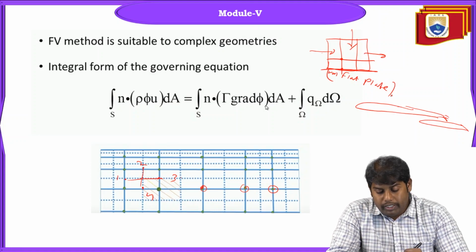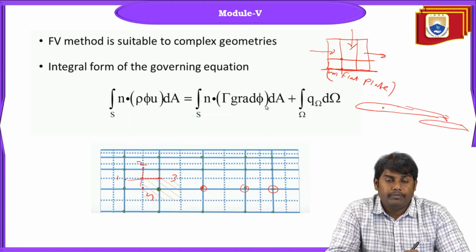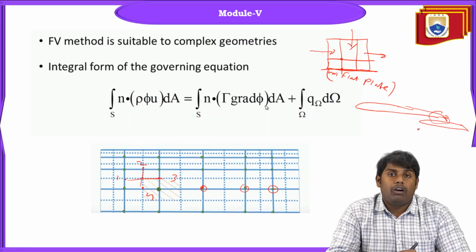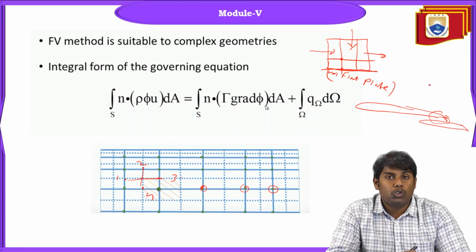Why? You have the curved nature and some intersection, and you have two different airfoils, or let's say two differently shaped or sized airfoils, which are attached together. During intersection, the mesh has to be generated here also, and that would be a hectic task. So people use a combination of structured and unstructured mesh: where it is simple, they use structured mesh, and in places that are complicated, such as this intersection or the curved nature, we use the unstructured mesh.